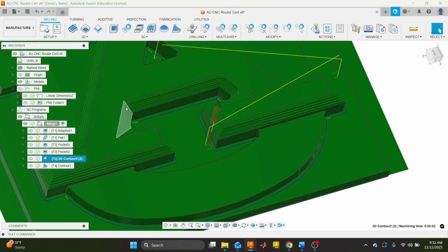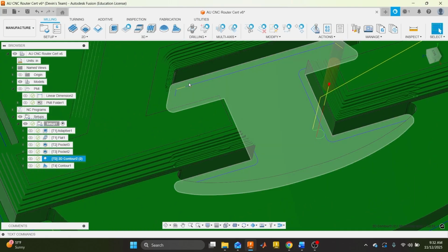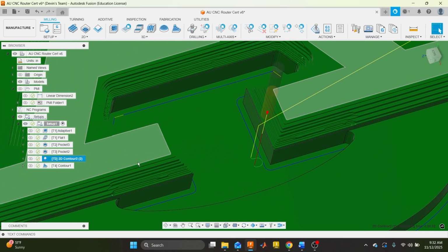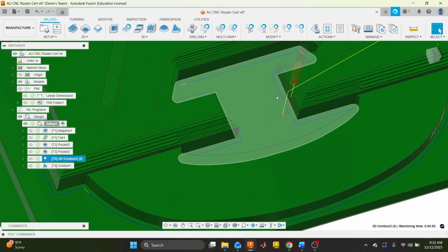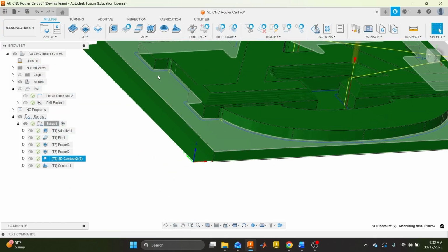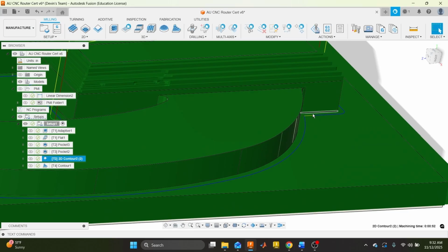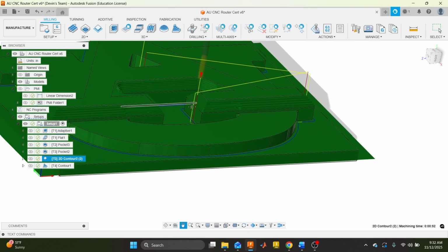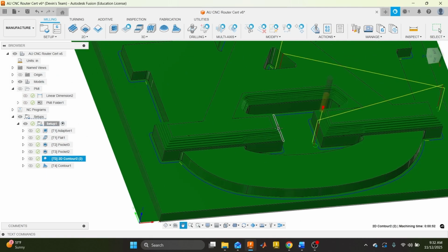and then we're going to move it to a contour operation, and that is going to take the radial dimension down to what it needs to be for the piece. So now we have removed all of the stock from the radial dimension just by going in and selecting this contour. You'll notice that the blue machining lines turn yellow for these internal corners. That is what we call feed optimization, and I'll get into that in a later lecture.